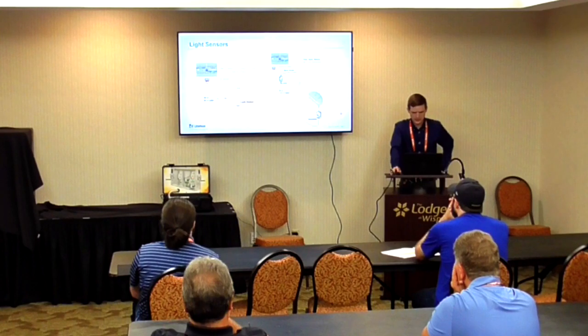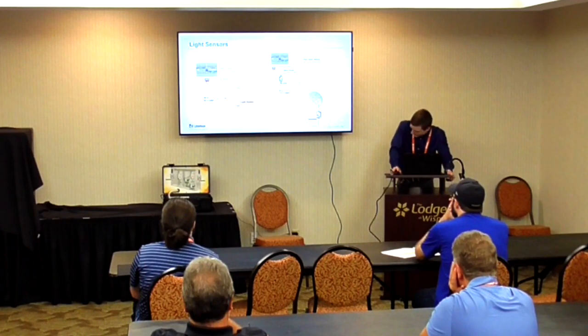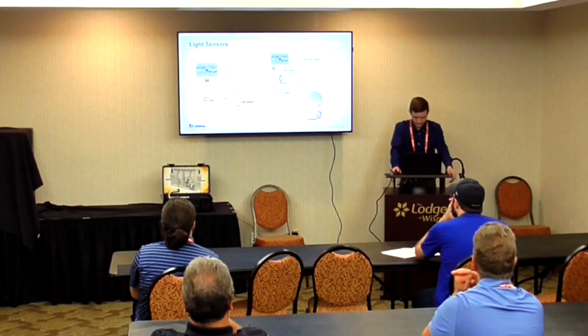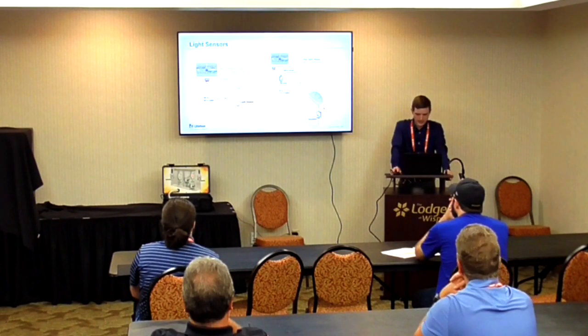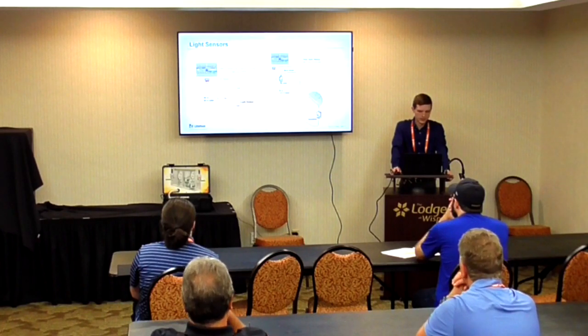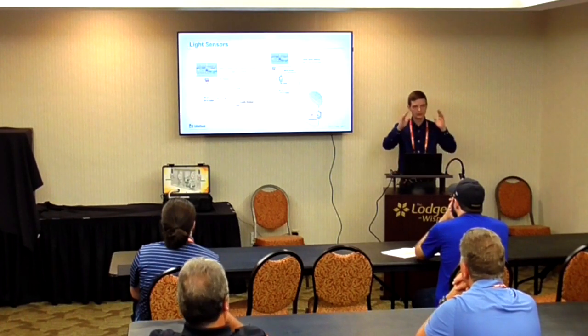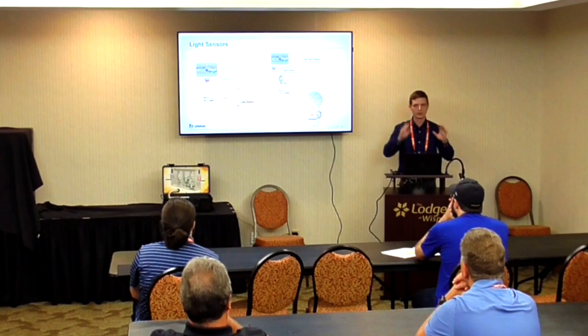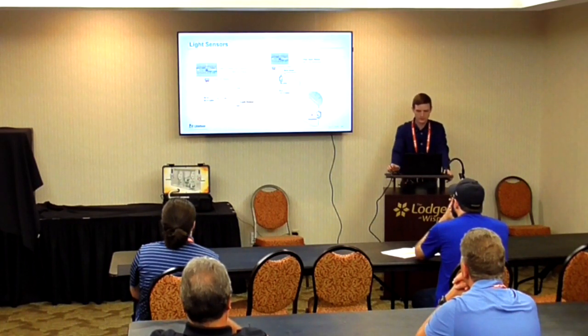And for fiber optic cable, this actually monitors for light along the entire length of the fiber optic portion of it. So this is very good in the event that you have a bus bar that you want to monitor along the length of it, or if you have an enclosure with a lot of obstacles and things like that where you don't want to have 6 different point sensors in there, you can just run a fiber optic cable through it, and I'll actually show you a picture of that in just a minute.